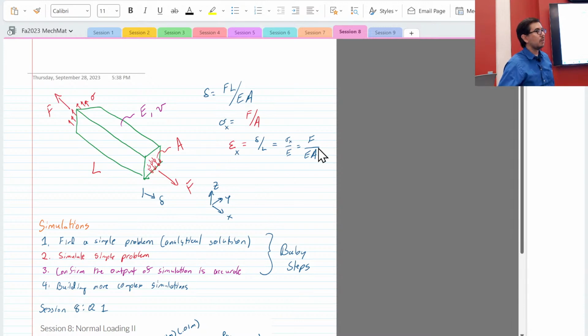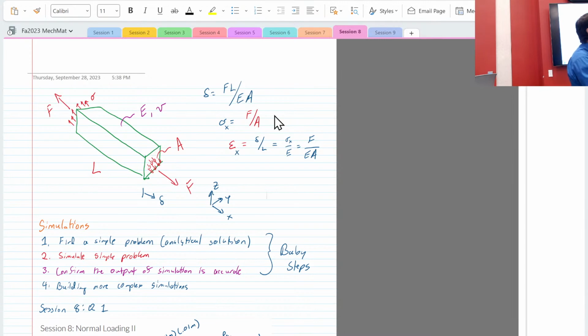And so you've got a number here, and it's F over EA for the first one. This was last week. Okay, well, you're telling me it's off, so it's got to be off from something, right? When I did it by hand, I got it right, but it didn't line up with what the finite element analysis was telling me. Okay. When you measured the strain, where were you measuring it? At the opposite end. Okay. Where the force is. So try moving over a little bit.